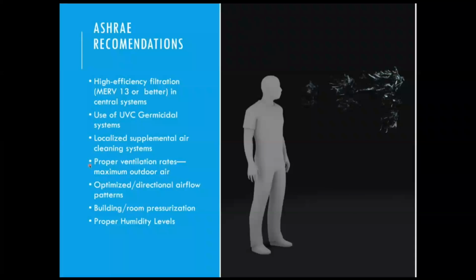The good news is with viruses, flu viruses, it doesn't take that much UVC to inactivate them. They're down at the lower range of 3,000 to 4,000 microwatts. Spore-forming bacteria and molds take quite a bit higher dosage, maybe several dozen times that level.